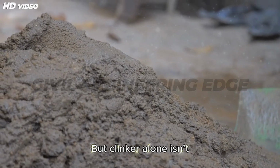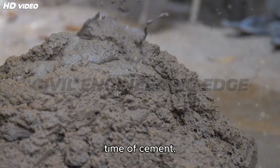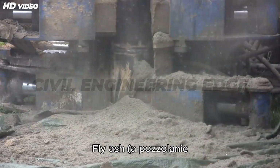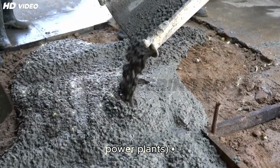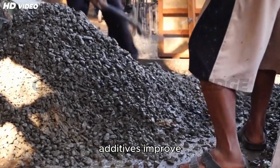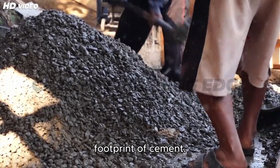The clinker alone isn't enough, so it's blended with 5% gypsum, which regulates the setting time of cement. Depending on the desired properties, the clinker may also be mixed with fly ash, a pozzolanic material from thermal power plants, ground granulated blast furnace slag (GGBS), or limestone powder. These additives improve strength, durability, and workability while reducing the carbon footprint of cement.